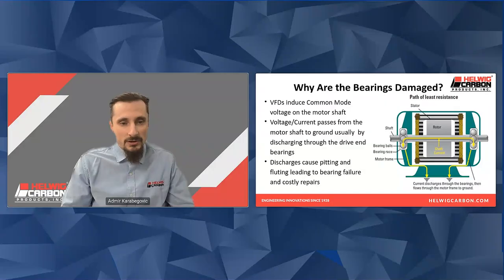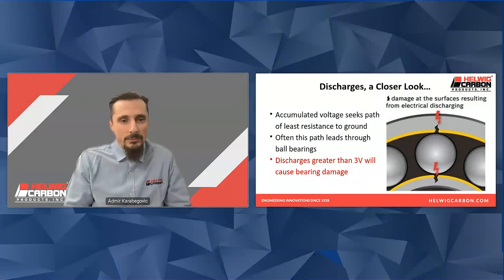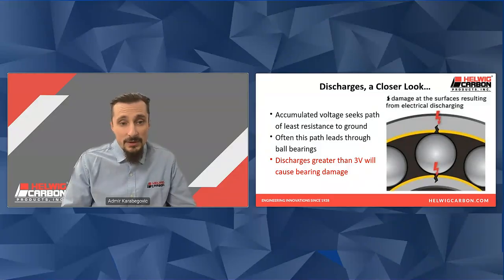These discharges cause the pitting, fluting, and eventual bearing failure, which lead to costly repairs. Accumulated voltage obviously seeks the path of least resistance to ground, and this often, again, happens right through the ball bearings. Generally speaking, discharges greater than 3 volts will cause bearing damage.